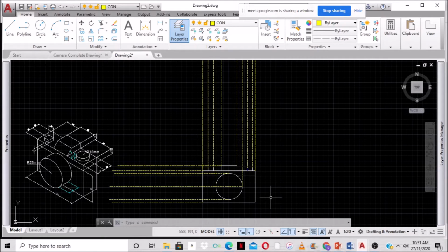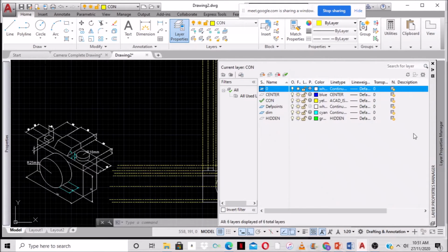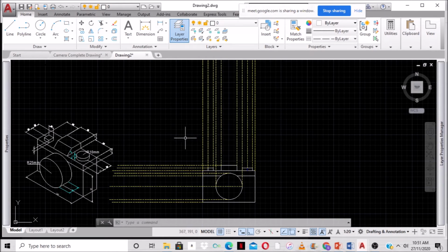Yes, sir. All right. So now we want to draw the plan, right? So we're going to go back here. We're going to select the zero layer, turn on the zero layer, right? And for example, we're going to just draw a line, select a line, and go above this drawing. You see that it's not allowing you, so you have to go to the midpoint. So you can go to the midpoint and you just go across and hit your space bar.